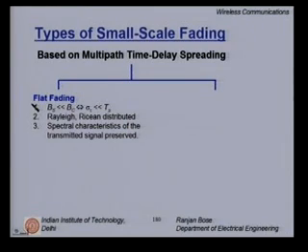So, we are trying to comment something about the nature of distortion that we get vis-a-vis the frequency of transmission. Frequency flat fading occurs when B subscript S, which denotes the bandwidth of the signal, is much smaller than B subscript C, the coherence bandwidth. This implies that sigma tau, which is the RMS delay spread, is much less than Ts, the symbol duration.